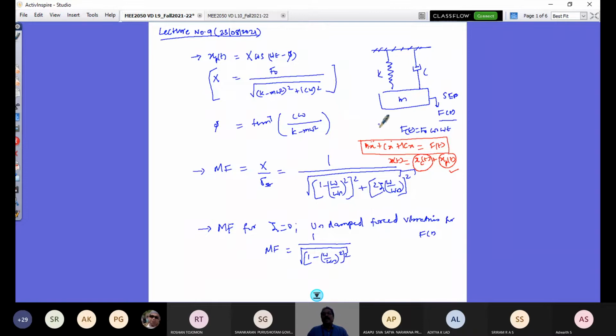The elements are mass, spring, and damper, and the damping here is an underdamped system. The zeta value less than 1 refers to an underdamped system, where you will have a harmonic oscillation. Whereas if the zeta value is 1 or greater than 1, it is aperiodic, and you will not have a vibratory system. This is the background on the significance of damping in the system. Damping present in the system is not conservative; there is a damping force, and that force dissipates energy in the form of heat or sound in the vibratory system.